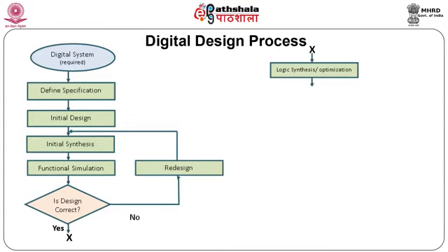Once the functionality of the correct design is obtained, the next step is to use logic synthesis and optimization tools. This stage will help the designer to work on parameters like speed, cost and device technology for the implementation.